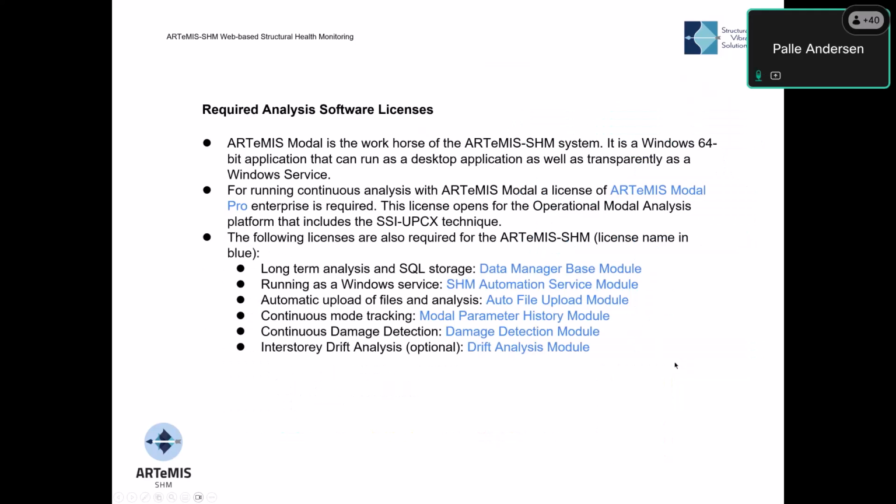There is a bunch of licenses that are required in order to make this run when it comes to ARTeMIS Modal. You have to have the ARTeMIS Modal Pro Enterprise version of the software running. This allows you to do operational mode analysis. But besides that, you will need something that allows you to analyze multiple measurements in the same project. To do that, there is something called the Data Manager Base module that configures ARTeMIS to be able to analyze continuously the same project over and over again with new data.